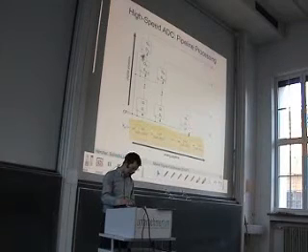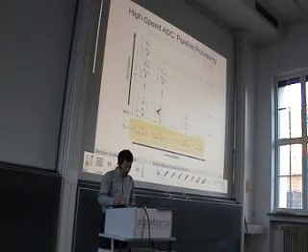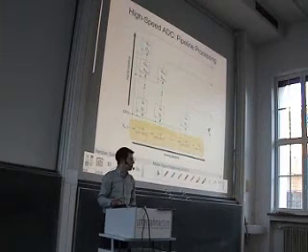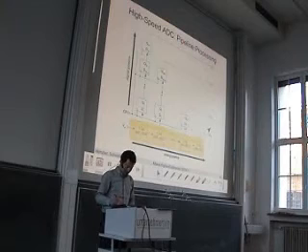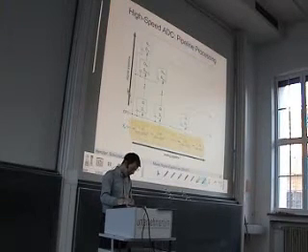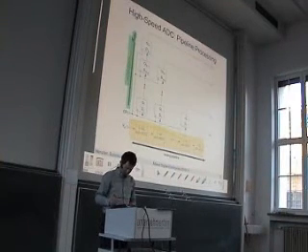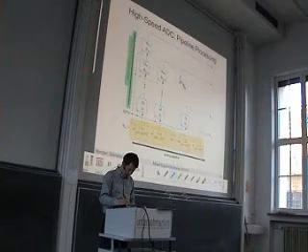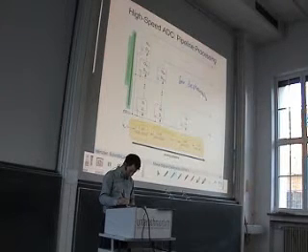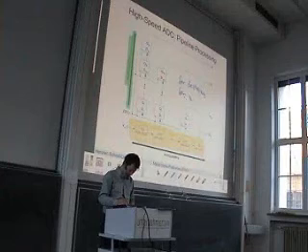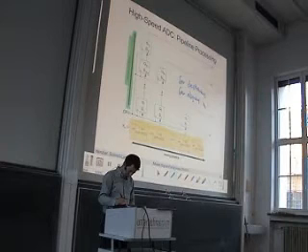However, for the MSB we need the most delay elements, and then we come down by one delay element in each step, and finally the output stage does not need any delay element. We have therefore in this direction a digital pipeline, and this is important for queuing, or you can say for aligning of result bits.